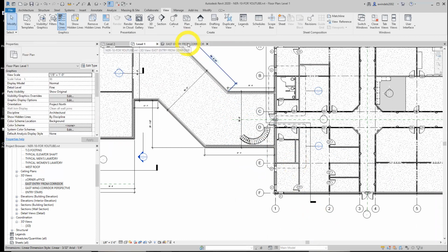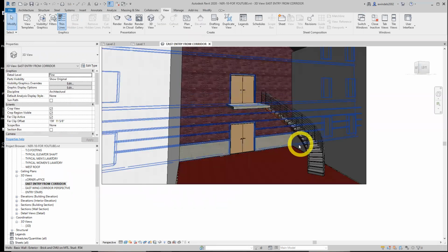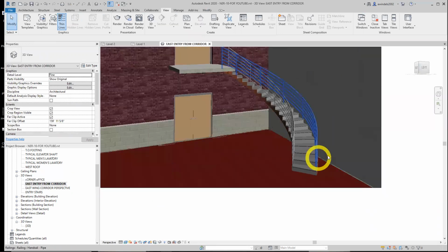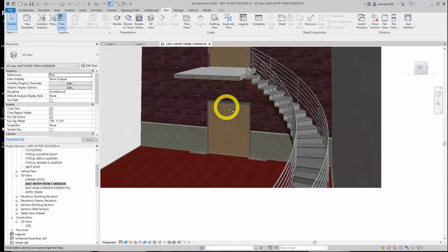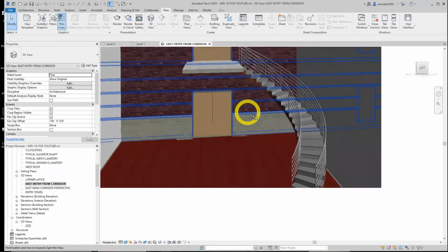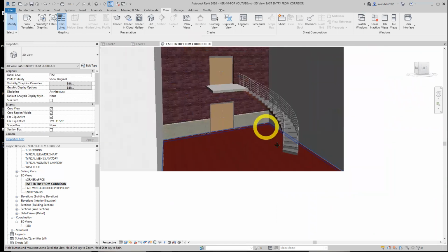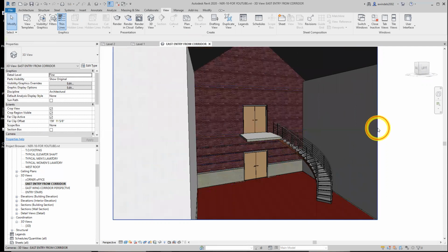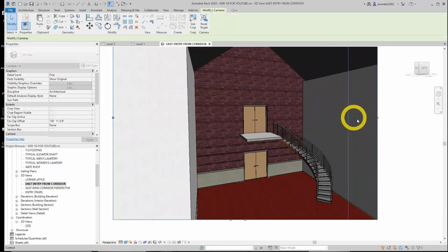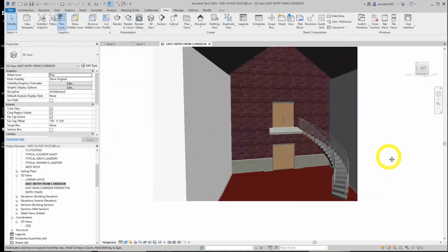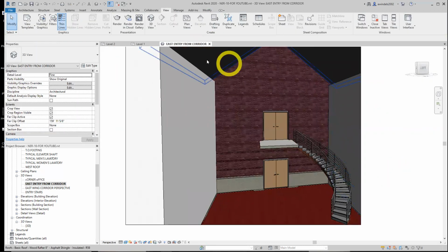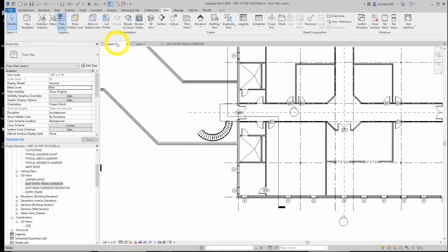Since I already made it, you click, edit the boundaries of it. So you can see the stair I made and the railing. You can rotate around with holding shift and center mouse. Change your grips if you need to on the outside of this camera view. Check your work, basically. So we'll go back to level 2. Made the camera view, cool.